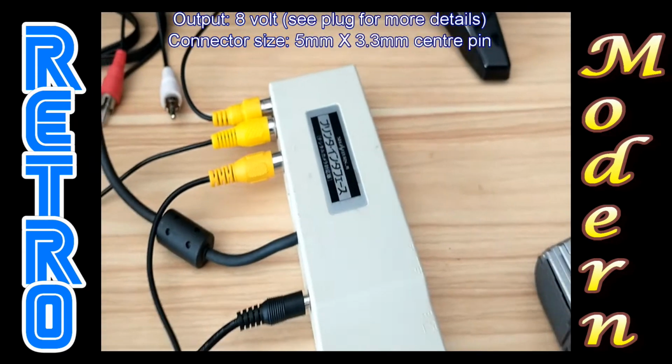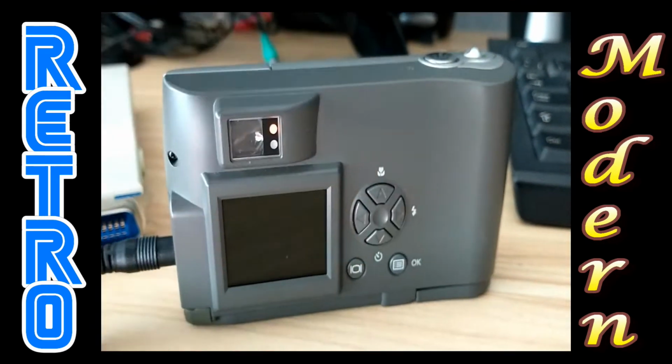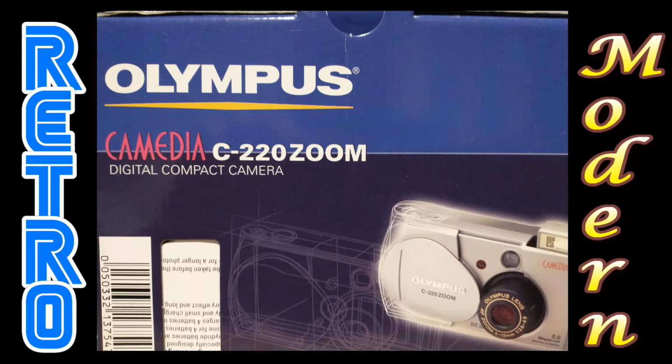Next you need to turn the digital camera on. Now one issue I had is when I connected my digital camera, you could see it on the screen when you flipped over to it using the Sega Saturn and you could look through the pictures, but when it came to transferring the pictures to the actual Sega Saturn, it wasn't working properly. And what I figured out is that because my camera was a PAL camera and the video out was PAL, it wouldn't work with it.